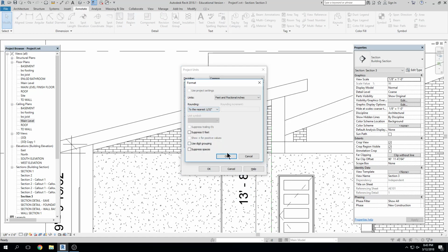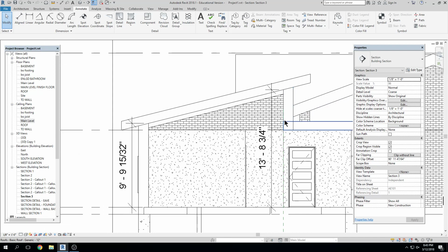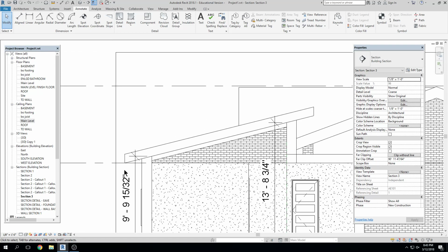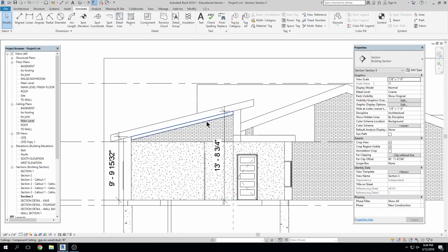But I mean, in my defense, I think our units are set to a 30-second. One question, so when you were entering all those numbers for the ceiling when you were in the sketch mode, you were putting these numbers that you measured. Your ceiling went above everything. It was probably set at top of wall or something, and so it actually formed like 9 foot 9 above that top of wall. Yeah. So above main level. Right, exactly. So I just moved it down.